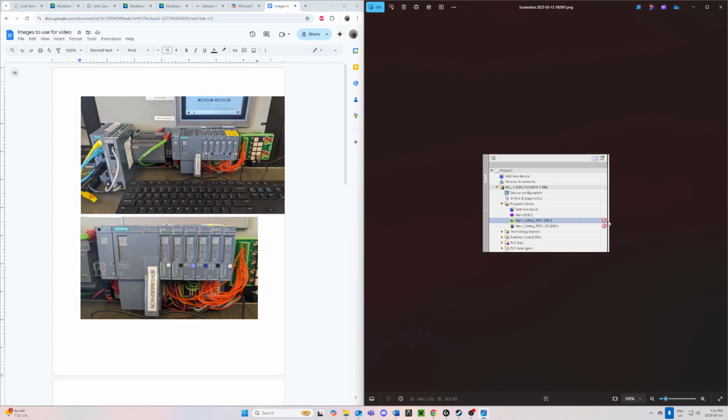And then you will see two crosses over two safeties. You will be deleting these from your main OB program blocks under the PLC listed that you initially selected. Under program blocks, underneath main, you will want to only keep main OB1.